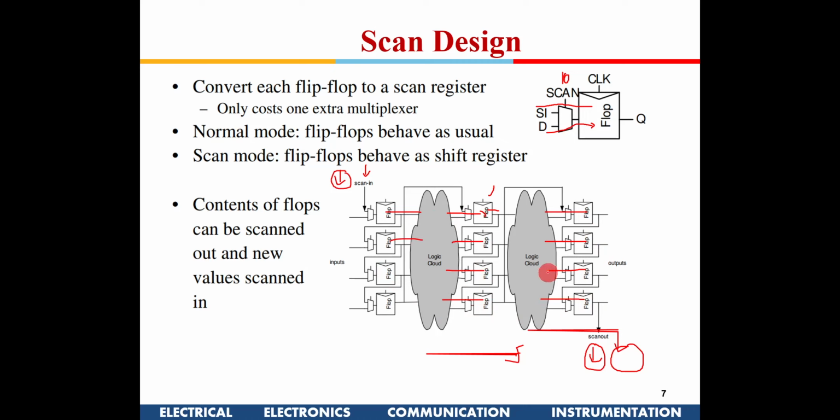So in the scan design, earlier we thought that by putting these things in, we were only trying to find out whether the combinational logic is good. No, that's not the case. Actually, we can also test these flip-flops.